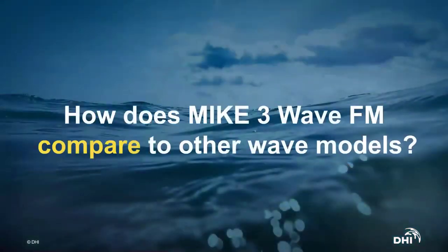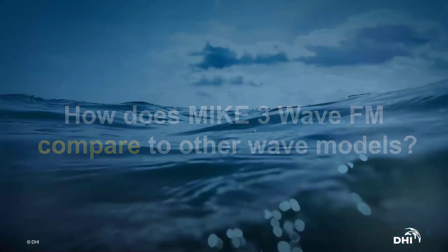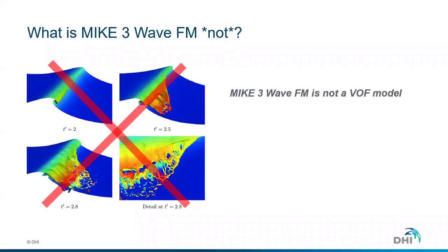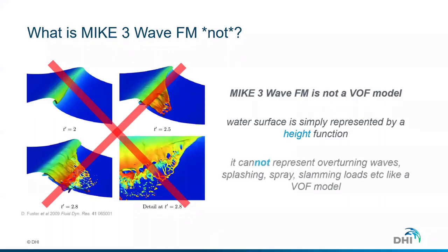All right, so let's talk about MIKE 3 Wave FM compared to other modules. First of all, MIKE 3 Wave FM is not a volume of fluid method. We are not trying to resolve some of these splashing phenomena that you can resolve using a CFD volume of fluid method.